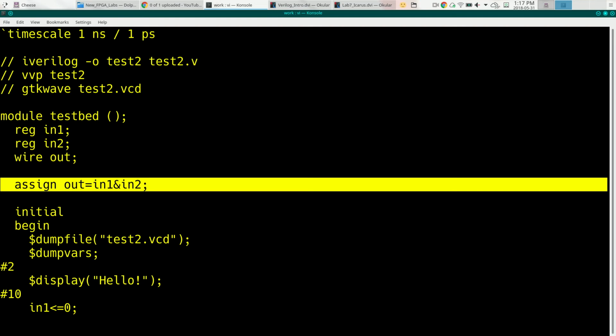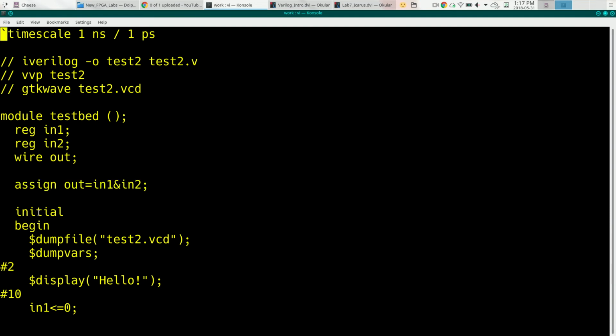So we're doing something here which is not synthesizable. What we put in this part of the module is not something that gets turned into hardware. These are instructions that can be used to simulate the behavior of our circuit. So we got to kind of get a little two-sided here in our thinking of this. The first set of code, that synthesizes into a piece of hardware, an AND gate in this case. When we say initial, we're listing things that we want to have happen when we start simulating this. They're kind of initial conditions.